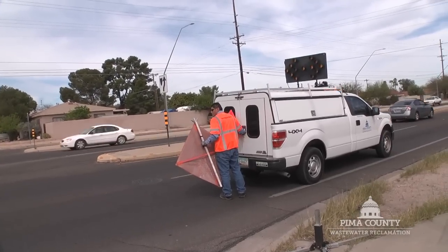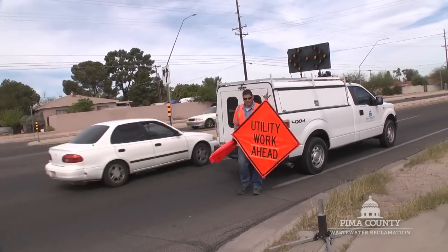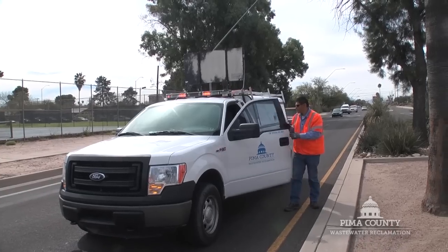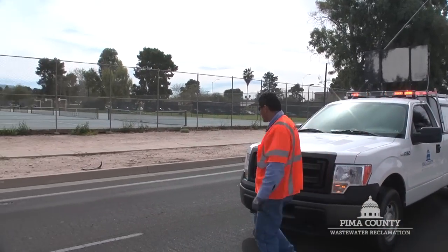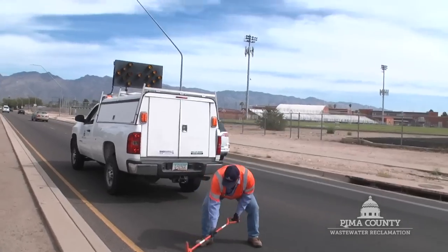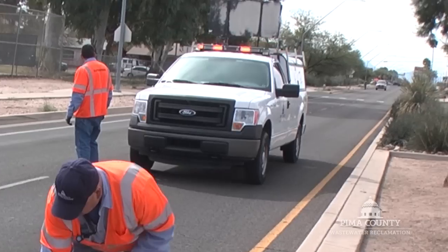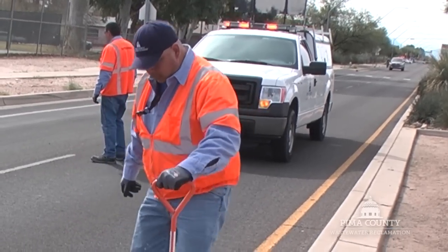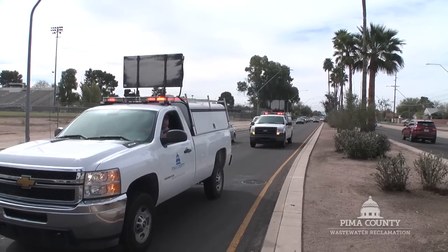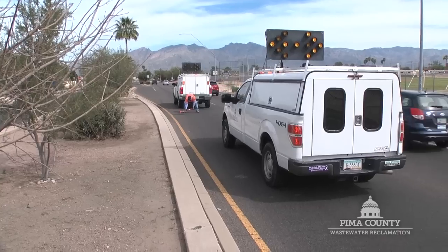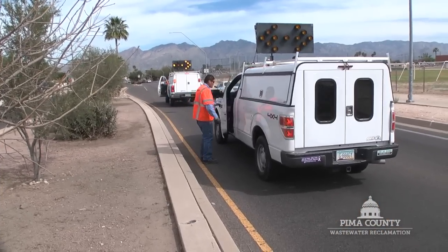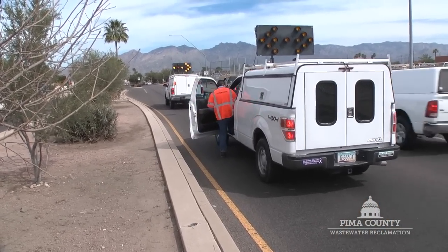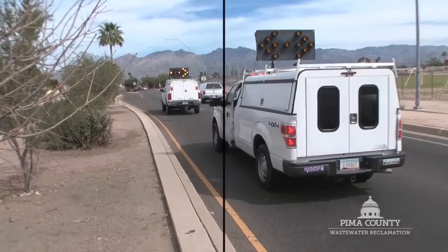Occasionally, the work crew may need to conduct mobile work or mobile operations, each as much as 15 minutes long, for activities such as visual inspections and spraying manholes, which often involve frequent short stops. Warning signs, flashing vehicle lights, flags, and/or channelizing devices should be used. Certain types of operations move intermittently or continuously and do not occupy a single area for prolonged periods of time.